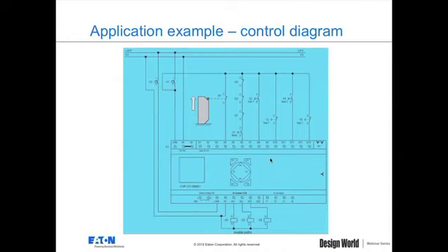So similar control diagram here. This device here obviously is the safety controller. On the top side here it's got 14 safety inputs, and on the bottom side here it's got 1 relay and 4 transistor safety outputs and 4 test signals. Right here is our single channel limit switch of just a single normally closed contact. We don't need to go to a dual channel because we only need to achieve a protection level C. Right here we have the reset chain, so this is going to give us again that monitored manual restart.